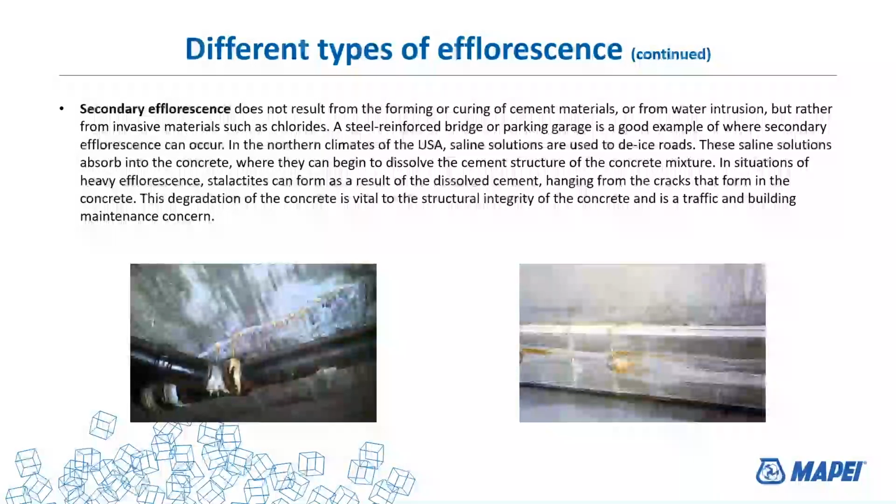In these pictures, I think they were taken on a job in Vermont. What happens is they were using salt solutions on the street to dissolve the snow. Those chlorides in the salt get into the concrete mix and cause problems. They start reacting with a variety of materials in the stone, in the brick, in the concrete structure. It could even be rebar inside, causing it to rust and causing even further issues.